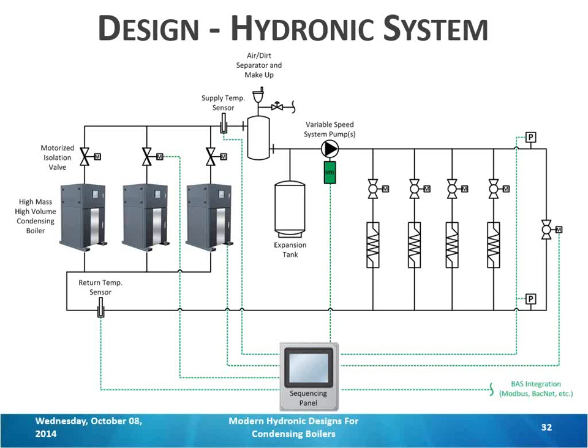Most integrated controls will just turn on the second boiler, bring them all on until every single one is on, and then modulate them in parallel. Typically, you'll need a standalone panel that has the logic to bring the first one up a little bit.